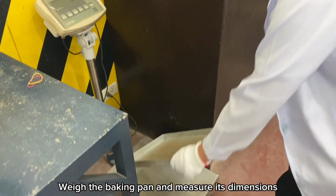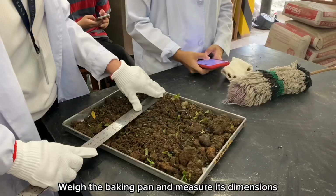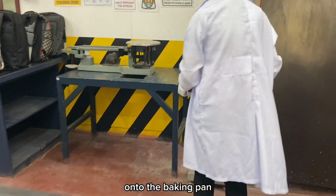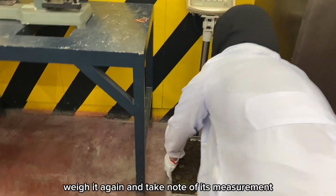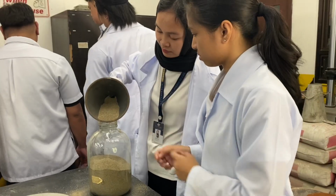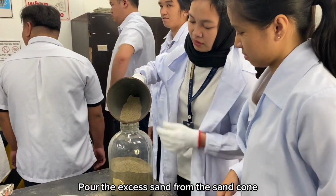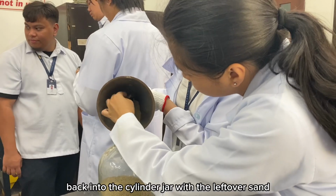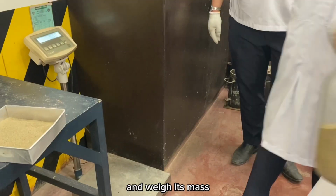Weigh the baking pan and measure its dimension. After putting the soil sample onto the baking pan, weigh it again and take note of its measurement. Pour the excess sand from the sand cone back into the cylinder jar with the leftover sand and weigh its mass.